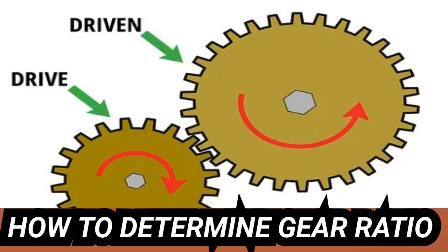To see the principles of gear ratio in action, take a ride on your bike. Notice that it is easiest to go up hills when you have a small gear in front and a big one in the back, while it's easier to turn the smaller gear with the leverage from your pedals. It takes many rotations to get your rear wheel to rotate compared to the gear settings you'd use for flat sections, making you go slower. A geared down system, where load RPM is less than motor RPM, will require a motor that delivers optimal power at higher rotational speeds.